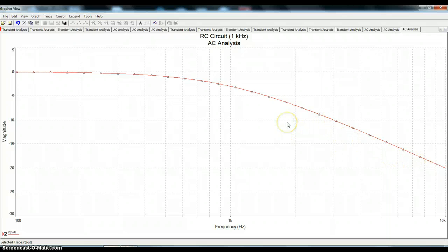This one pole low pass gives a roll off rate of minus 6 dB per octave, meaning every time you double the frequency, you go down 6 dB, or at least you approach the asymptotic behavior. Right in the region just above cutoff, it's a so-called cutoff, not really a sharp cutoff. You don't really get that effect there, but as you move farther out, you really do.